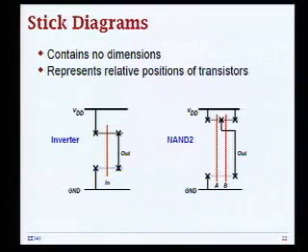So that when you do your logic synthesis, you can basically pick out which of these cells is the most suitable for the environment of your design. So basically, if you have a large fan out, you're going to use the stronger cell and so forth. And then you can do all the routing at the top level for that.